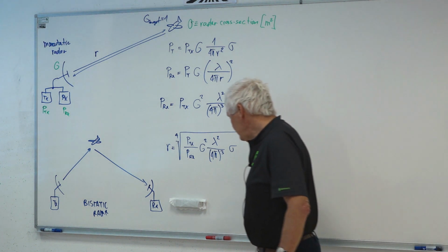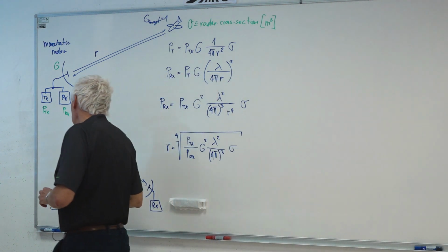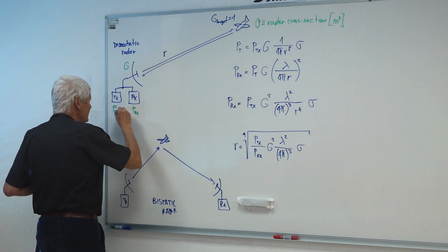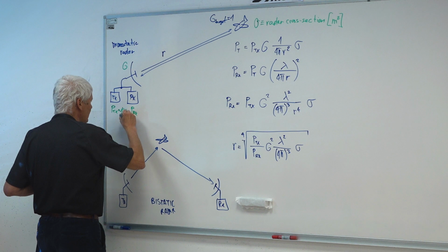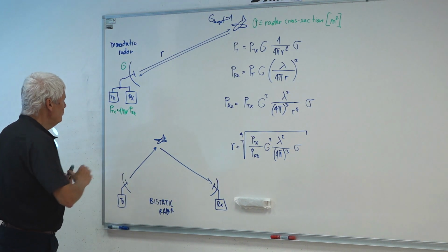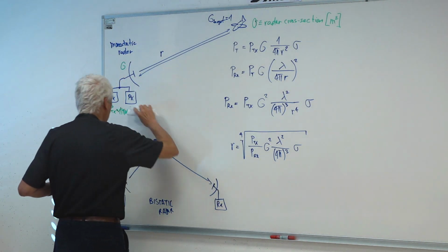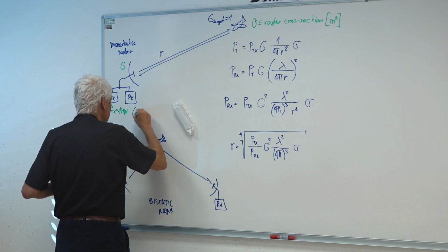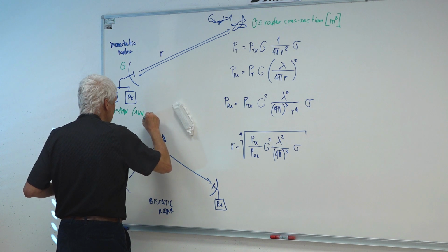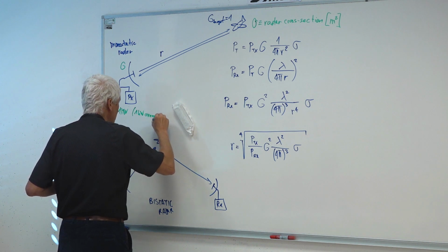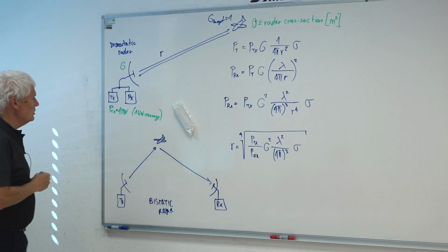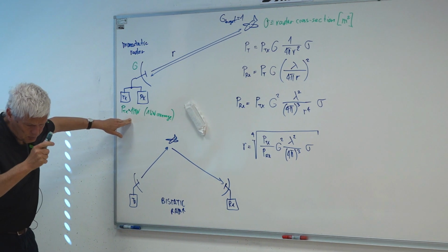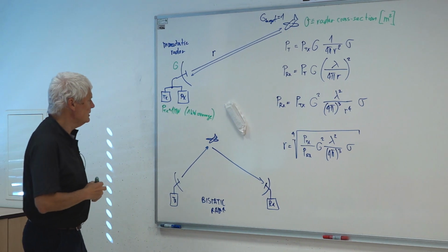What the power might be. What are the issues that I have? The transmit power for pulses may reach 1 megawatt. 1 megawatt is not a particularly powerful radar because this is just peak power. This means 1 kilowatt average, which is not a particularly strong power. So I have 1 megawatt just in the peak, transmitting very short pulses and then having a very long period.